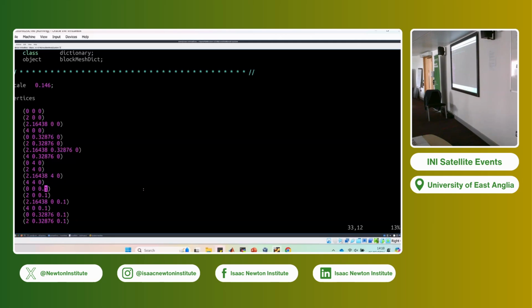I usually give a small domain size along Z just so that in paraview it looks quite two-dimensional, the geometry. Then this box to cell, you can give minus 10 power 9, plus 10 power 9. It doesn't matter as long as it's thicker than the actual extension along Z of the domain.